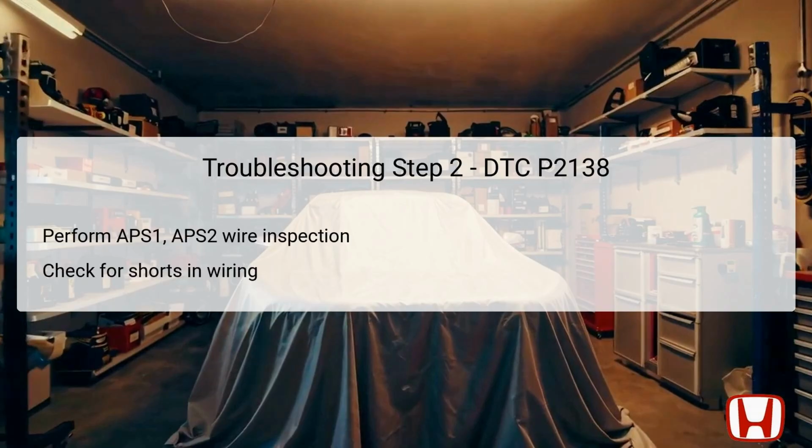This step focuses on inspecting the external circuit for the accelerator pedal position sensors. The APS1 and APS2 refer to the signals from the two sensors transmitting data to the PCM. Carefully examining the wiring connections and using a multimeter can reveal if there are any shorts or disruptions.